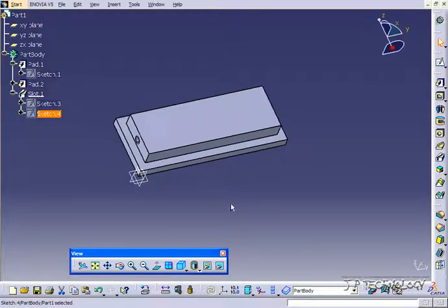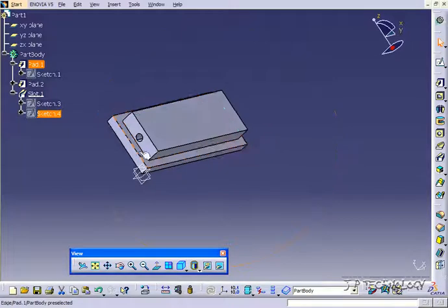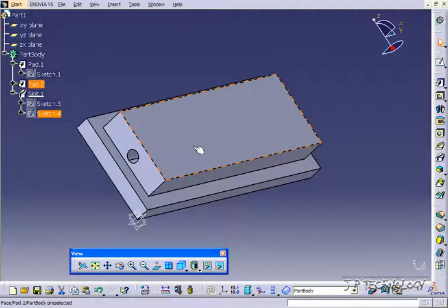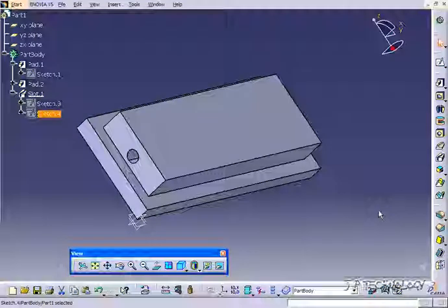So by using the slot feature in an application like this with a hole, you're able to have your dimension of what the hole is going to be, and then draw out and say where it's going to go through, say like a larger block. So kind of like a little pathway and everything for it. Again, this is a tool that's going to save you time, as you're able to create a complex path for it to follow along, and just create one sketch as the profile for it. And this concludes our tutorial on how to use the slot feature within CATIA V5.